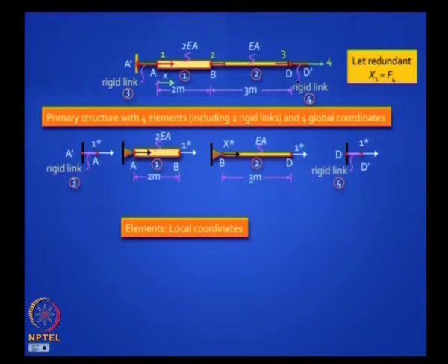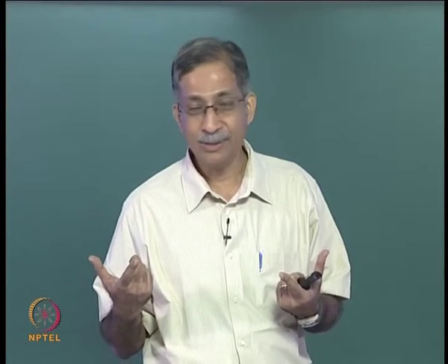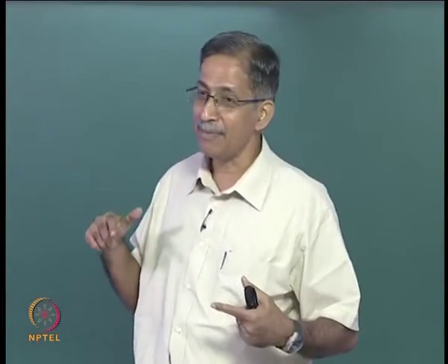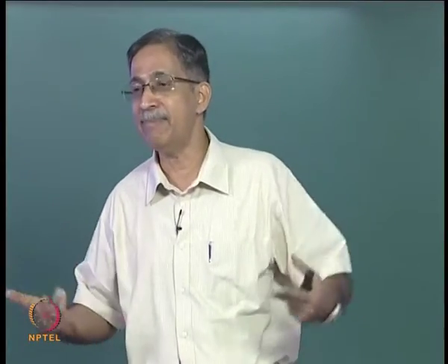Okay, I have now introduced two elements here. Elements 1 and 2 were there in the original structure. I have introduced here elements 3 and 4, and I am calling them rigid links because they are short links, infinitely stiff. Okay, the idea is the force in that link is my support reaction. So I am able to access support reactions by converting them as internal forces in additional imaginary members, if I